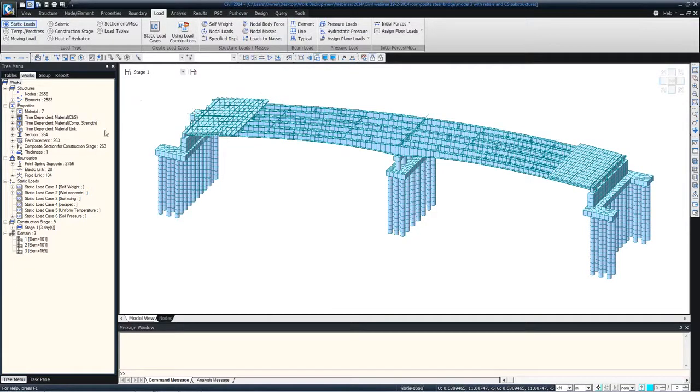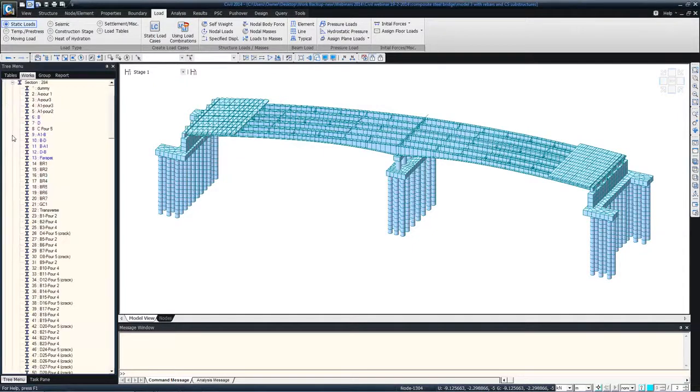Well, we first have to make sure that we have created nodes or divisions at every pour region, boundaries of the pour regions, so that we can assign those elements in a particular pour region with a given section name. So like I have named the section composite section based on the pour names.